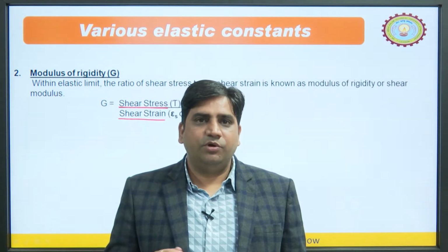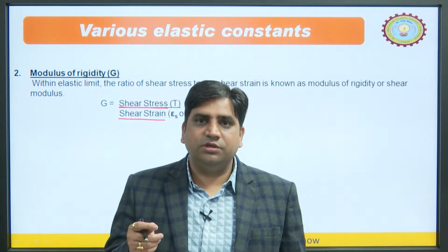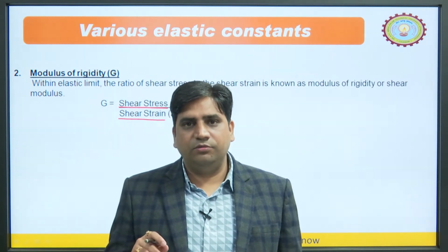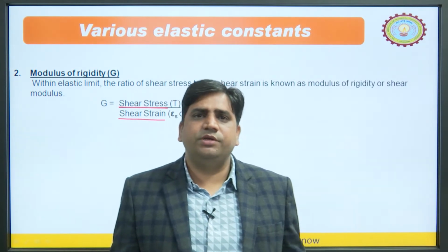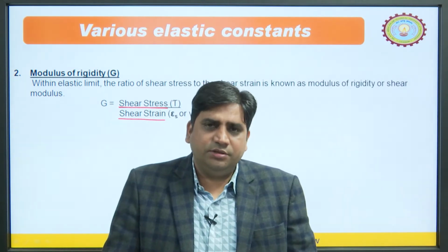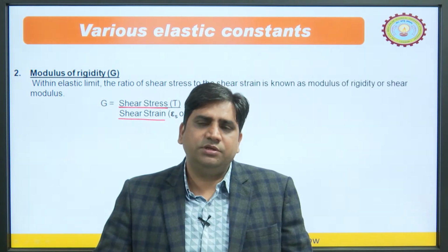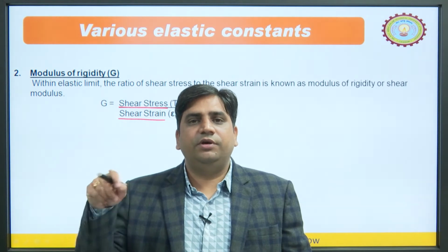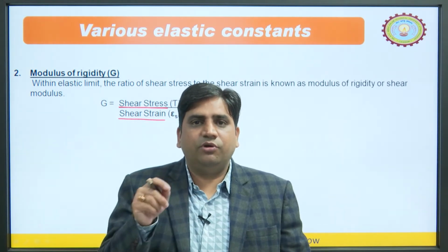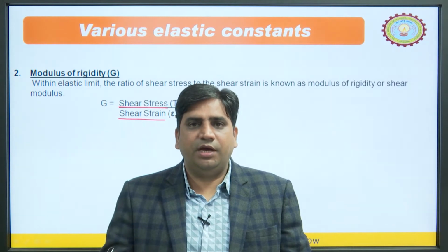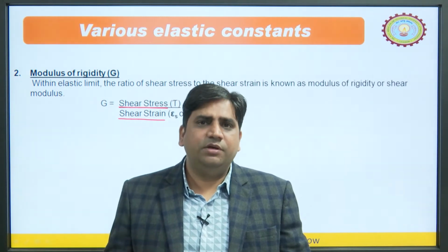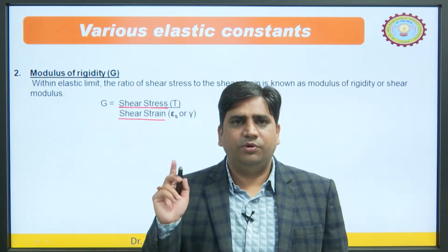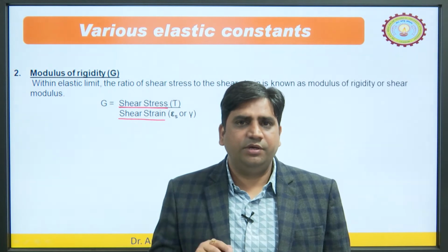So, modulus of rigidity controls how rigid the body is. In many situations we need a more rigid body, in many situations a less rigid body. According to this selection, irrespective of the shape, if you select a material for a particular application, its G would always be the same, right. Whether it is wire, sheet or pipe, the value of the modulus of rigidity will remain the same.